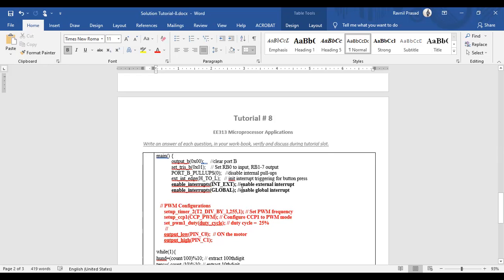there is no need for the initialization of the 7-segment display. We have already given the hex code. We have already defined it, so we don't have to worry about any other pin initialization over here. Then we move on to the proximity sensor, and then the motor. Motor will be the last thing that we want to turn on, right? Because if the motor starts and we haven't started the proximity sensor, the counting will be wrong, or it can give a wrong counting. Right?